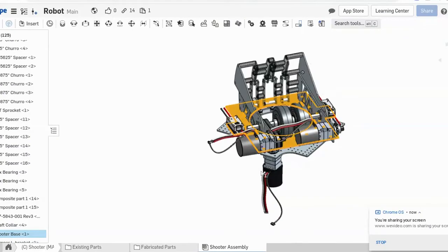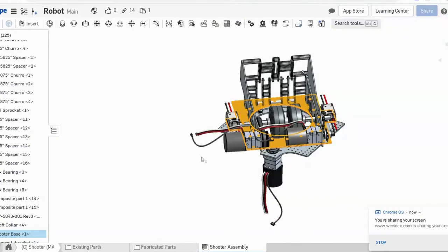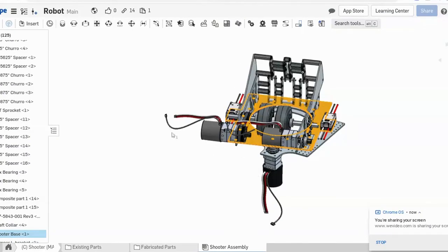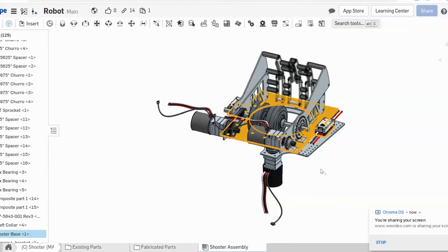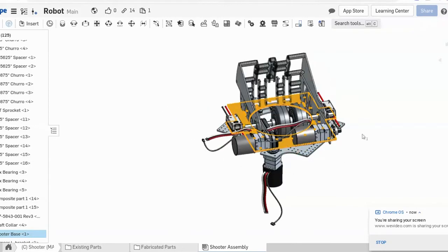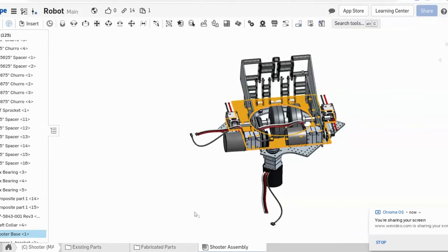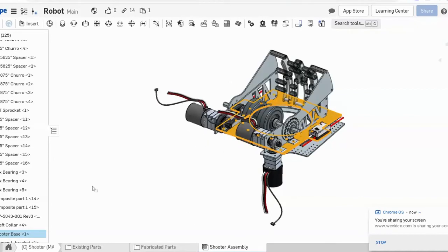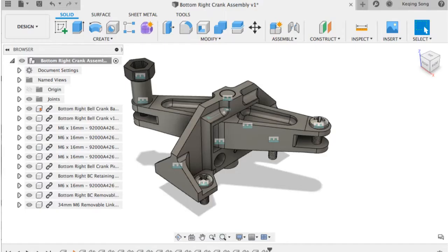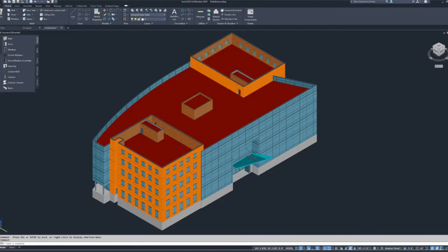Assemblies are also very important when CADing. Assemblies allow you to see how one mechanism would interact with another mechanism using constraints based on how they would act in the real world. This would allow us to know how feasible of an idea a specific subsystem or prototype would be for the final design.